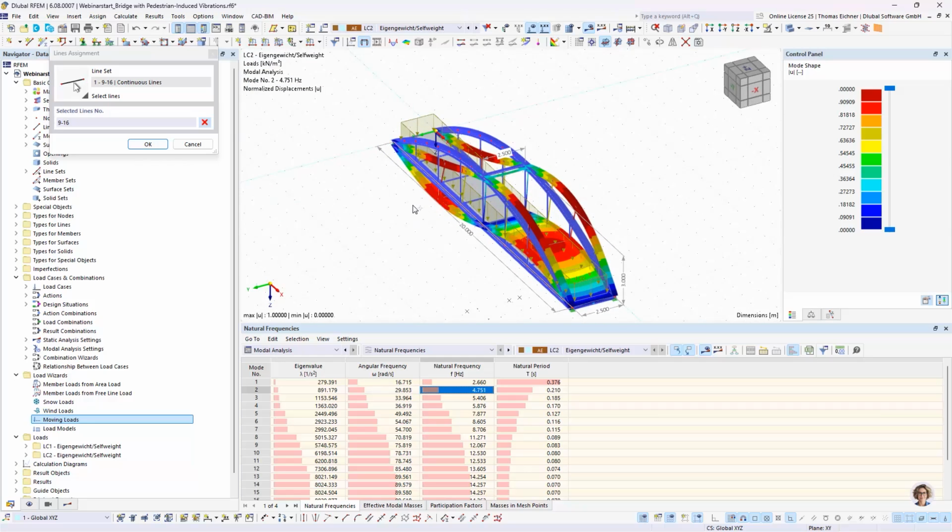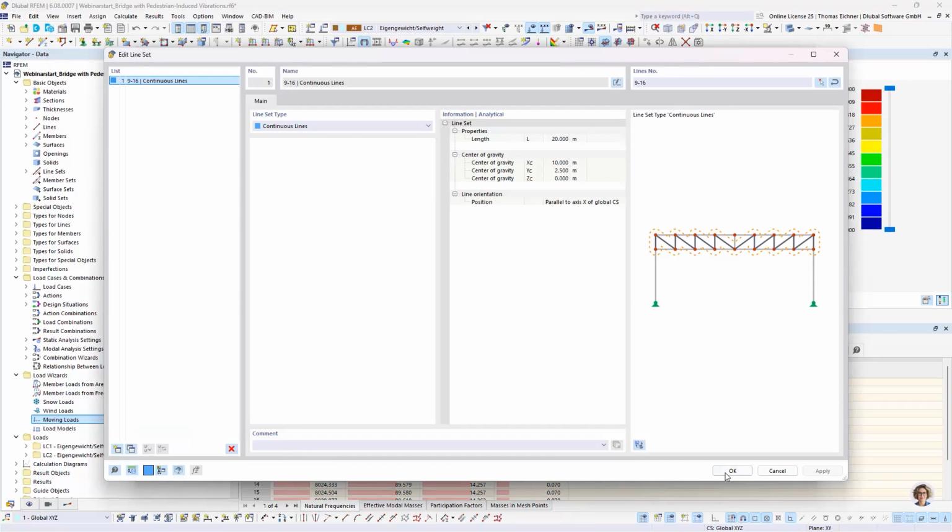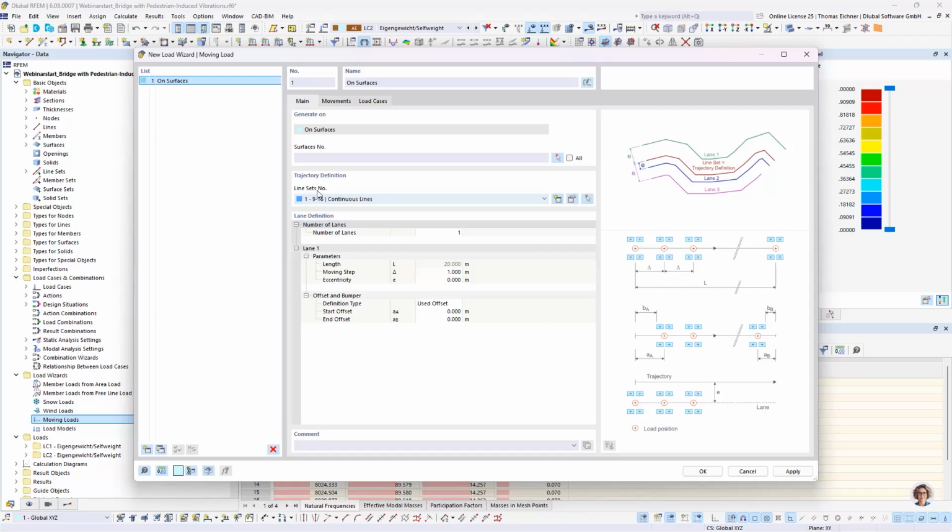And they are just the lines of the left side of our structure in this case. So we will set the parameters of our walker location with reference to this line. Quite simple. That's also called the trajectory definition. And we can also see it on this image on the right side below, trajectory line. So for the next step, we will have our moving step size.